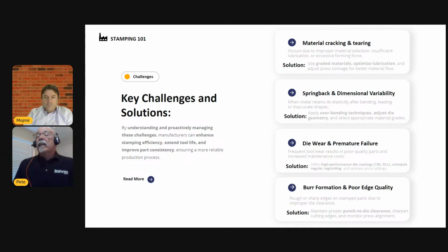As material gets stronger, we need a bigger lever, right? So we're going to need more clearance. Some of our advanced high-strength steels, 15 to 17% per side cutting clearance is the standard. I need a bigger lever to bend that slug. Now, the other thing to think about, too, are small holes.